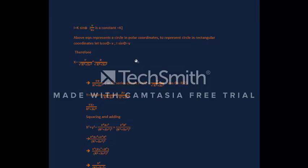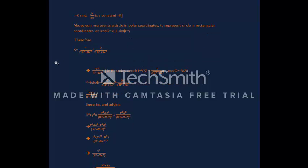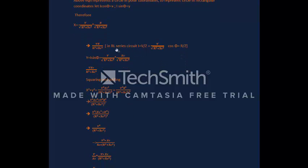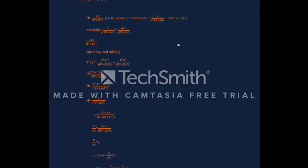And also the above equation represents a circle in polar coordinates. To represent the circle in rectangular coordinates, let's say I cos phi is equal to x and I sin phi is equal to y. Therefore x is equal to V upon root of R square plus XC square into R upon root of R square plus XC square, which turns out to be VR upon R square plus XC square. Also, in the series circuit, I is equal to V upon impedance, where cos phi is equal to R upon Z. Y is equal to I sin phi, which is V upon root of R square plus XC square into XC upon root of R square plus XC square, which is V XC upon R square plus XC square.